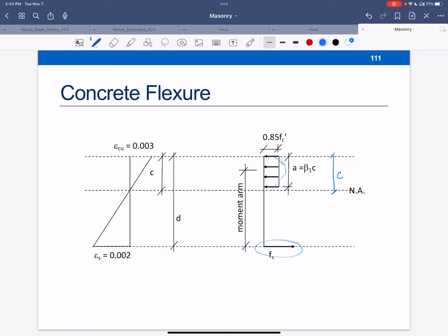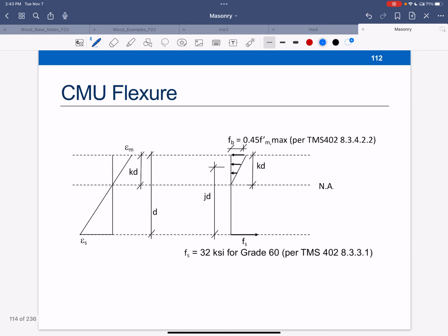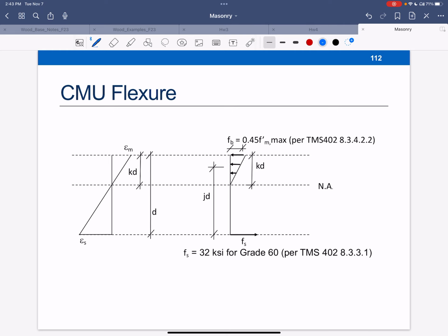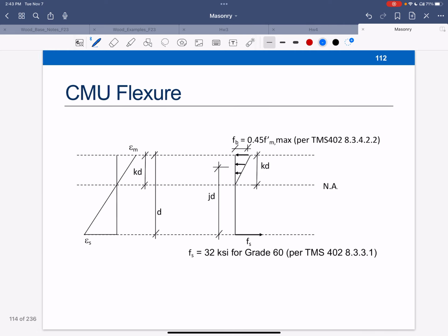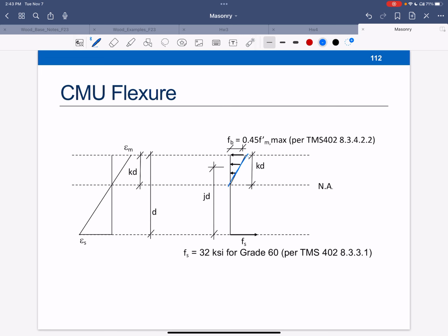There's a steel. I go to crushing strain and yield here. Why? Because I'm looking at ultimate. Not going to happen for masonry. So what do I have here? Now I have a nice linear stress strain curve. So I'm going to stay in the linear region. So I don't need the block because I don't have to approximate some weird parabolic shape. I just have a triangle.